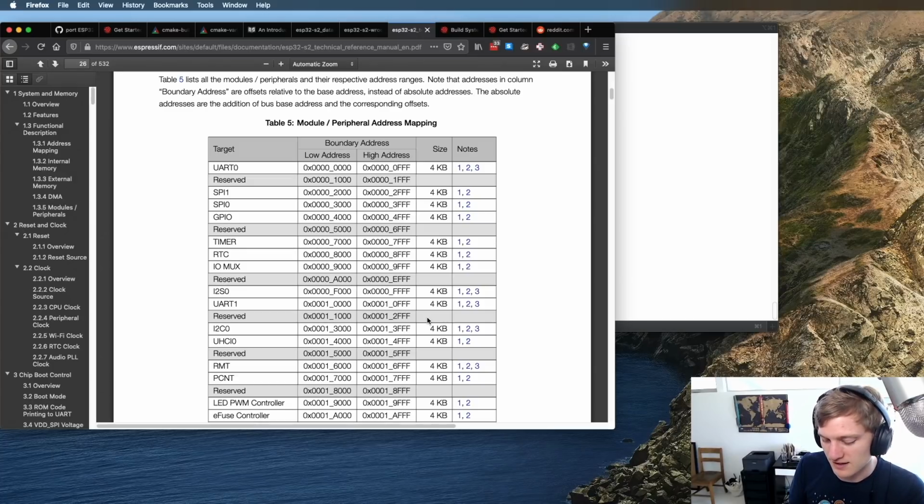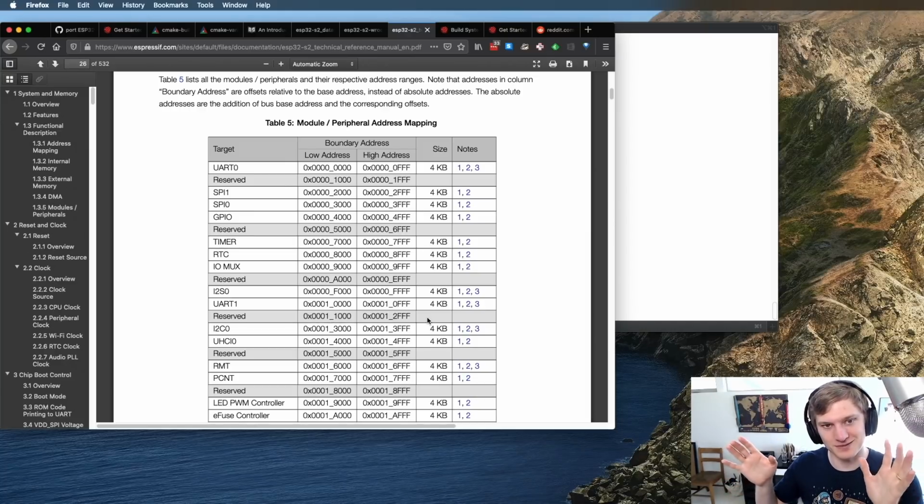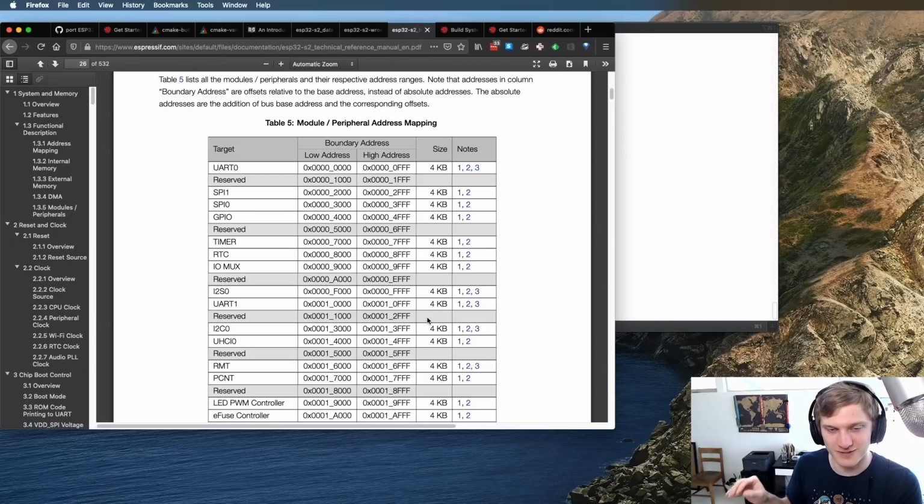It was that as he was doing SSL computations, there was a value in 32 bits that looked like it was part of the flash, but it wasn't actually part of the flash. So it would try to speculatively read the flash outside the range of the actual flash and then just hang because it wasn't valid.